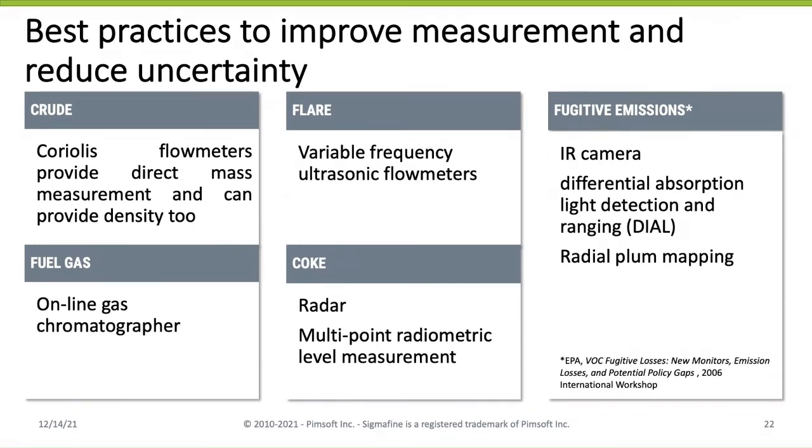On the fuel gas side, we mentioned a bit already about this. We suggest also having an online gas chromatographer, because it not only takes care of getting a proper composition correction, but also verifies the billing from an external provider. So typically you are purchasing gas from a supplier, but you want to cross-check if the heat content, which is intimately linked to the composition of the gas, is the one that is expected and that we are paying for.